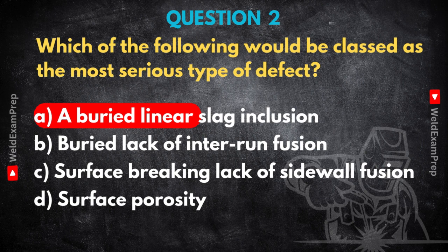That means it's a perfect starting point for a crack, especially if the weld sees any kind of fatigue or repeated stress. And the shape of that defect, that lack of fusion, is often sharp. That creates a stress concentration, like a tiny notch just waiting to grow. Plus, being open, it can corrode, which just makes everything worse faster. So it's exposed, and it acts like a weak spot where stress builds up, a real recipe for disaster. How do the other options compare then?